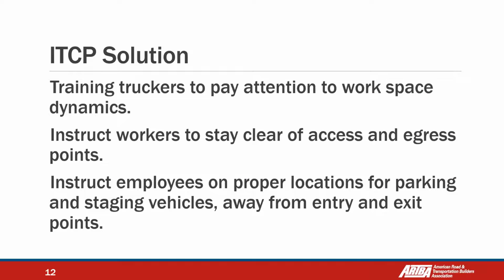Okay, some solutions that we have from the internal traffic control plan perspective: training truckers to pay attention to workspace dynamics. Okay, recognize how big the work zone is, what are the areas in which they have to drive inside the work zone, what are the distances when they are arriving, what is the access zone again. Then instruct workers to stay clear of access and egress points. Okay, we were talking about it, but we have to enforce it.